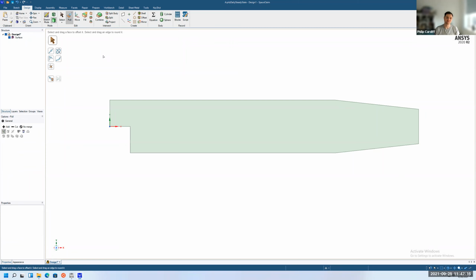So we want to use a structured mesh in this case. A structured mesh is like a perfect grid with squares. The mesher is typically only smart enough to do that if you split your geometry into 4-sided parts in 2D or 6-sided parts in 3D. So then, for example, if there's a small cube here, it will know how to put a grid on that. So to help the mesher, we're going to split this part.